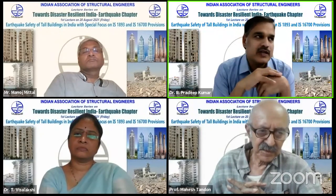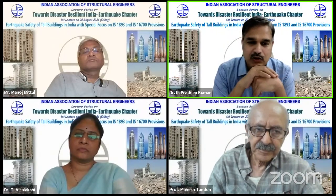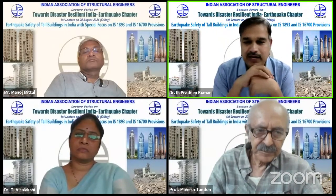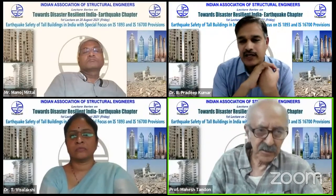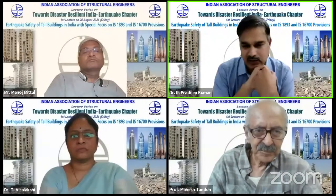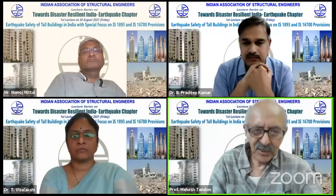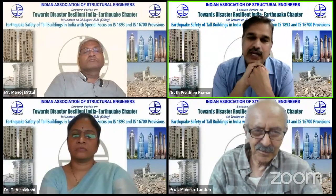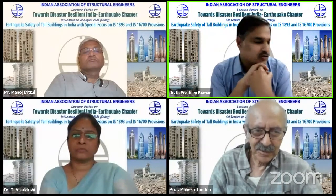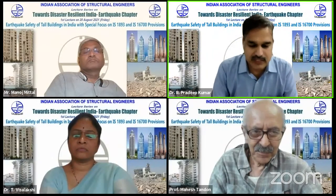Sir, drift check is gravity plus lateral load without load factors, unfactored loads. And do you take uncracked sections or cracked sections? Cracked sections. So there are two columns in Table 6.